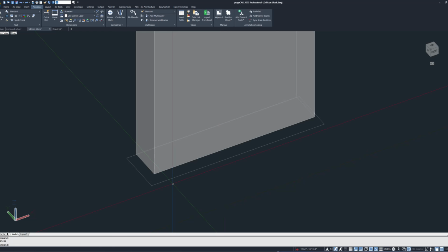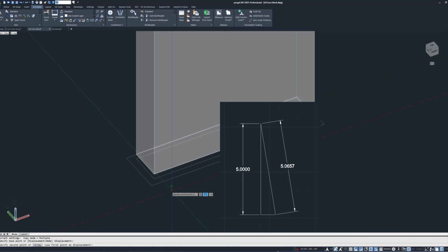Now that we have moved our phone extrusion below the bottom of the case, we can extrude it to the top of the box. You will see why we don't want to extrude it above the interior void in just a moment. The purpose of this current polyline box is to get a good height reference, because offsetting a line outside the exact dimensions of the box will not give the exact height. This illustration shows why.